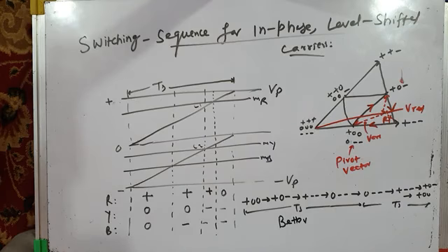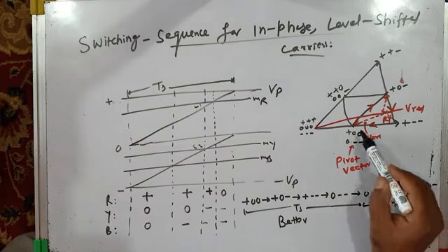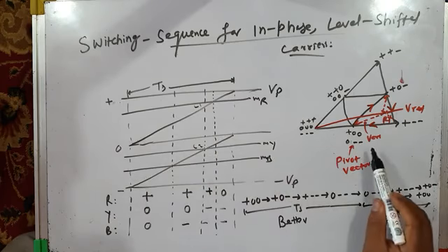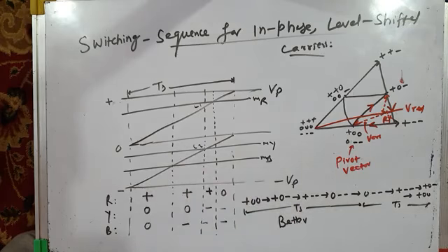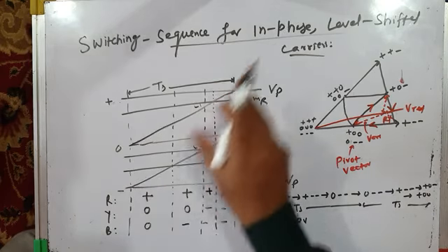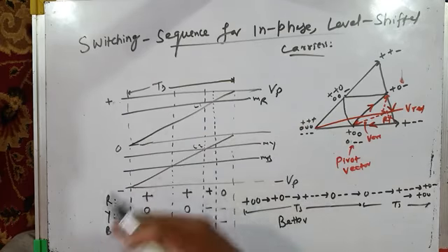Better harmonic spectrum. I had made some statement somewhere that the in-phase carriers will give very small error and hence low THD. Okay, low THD, in-phase carriers. You can say we have in-phase carriers. Maybe by mistake I gave a statement a few minutes back, or half an hour back, that out of phase level shifted carriers give better harmonic spectrum.